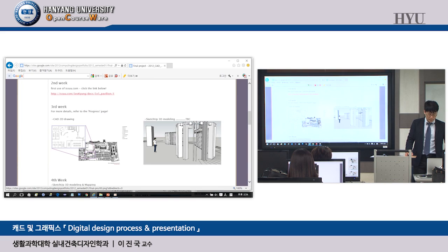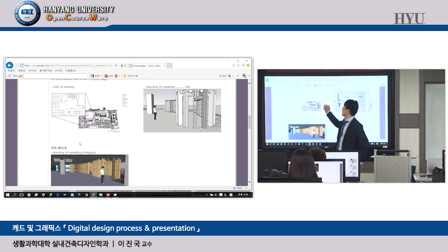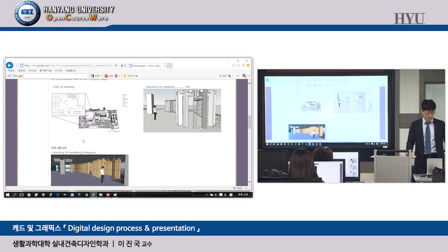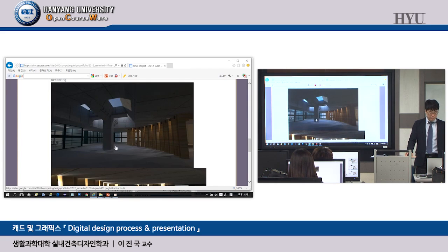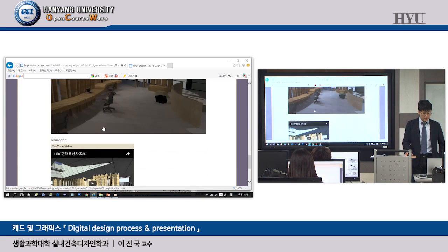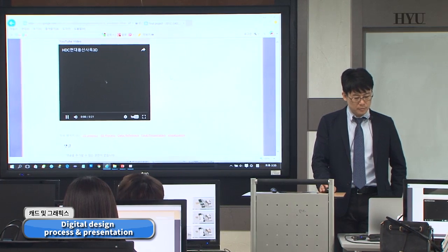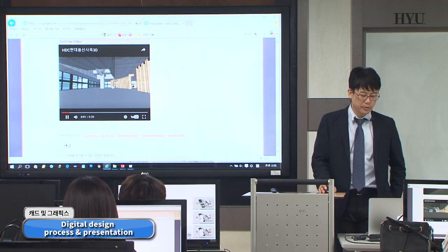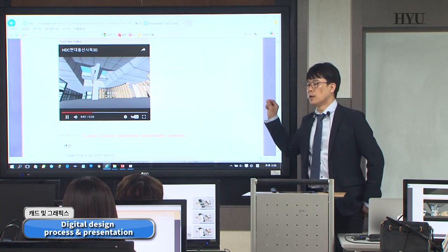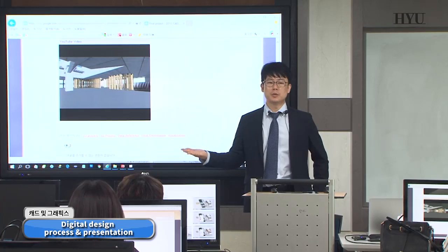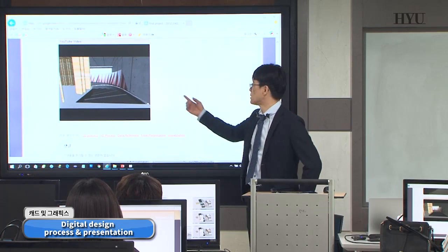Capturing the specific scene, okay? Actually, the floor is really huge. Instead, she focused on this area, okay? So that's why she tried to make this kind of ceiling structure, very unique ceiling structure, as well as this wood structure like this, okay? And the V-Ray render output is here, another V-Ray render, even animation. Animation created by scenes in SketchUp. What you need to do is add more scenes and export by animation. And then you can get this kind of video.